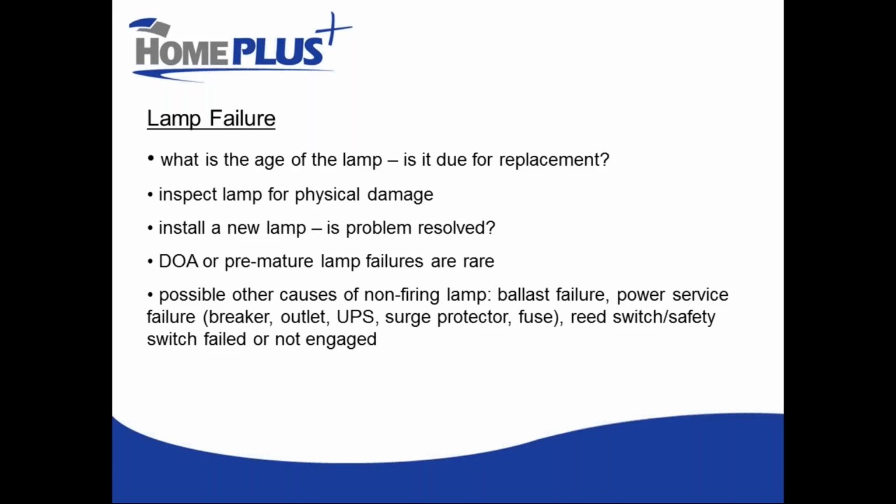Now, because you could have a left or a right-sided installation, depending on what side your pipes come in at or what side you want to mount your electronics on, you can actually reverse that lamp harness from a right to a left, and there's a separate hole with a separate reed switch on the other side. So if you have a UV Max Pro and it ever seems to be not firing for some reason, it could be related to a faulty reed switch.